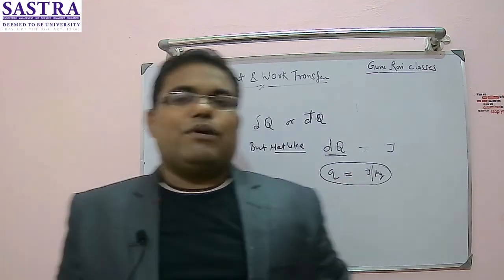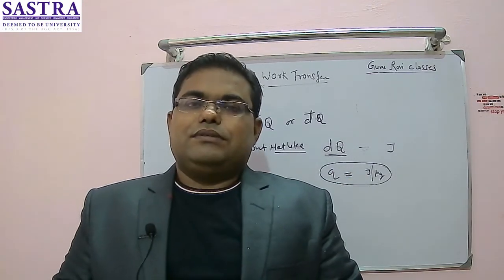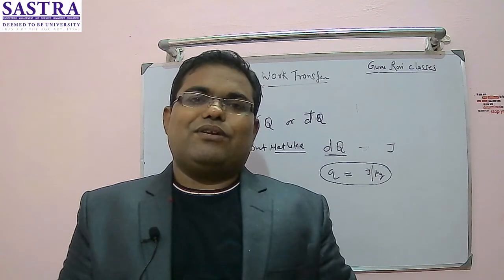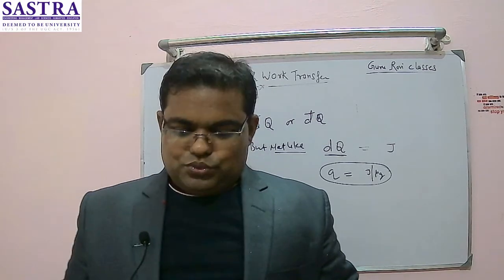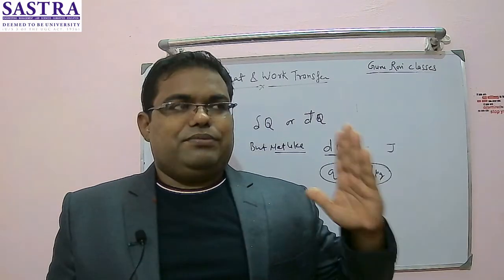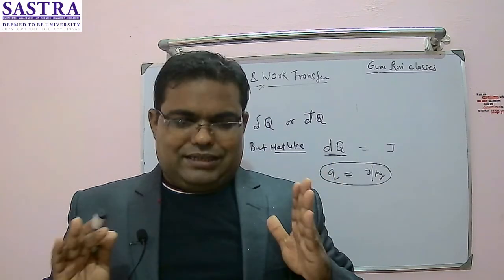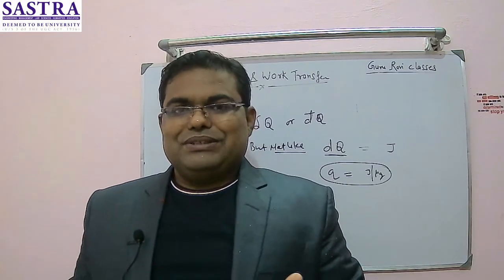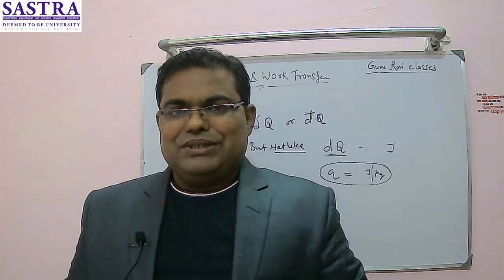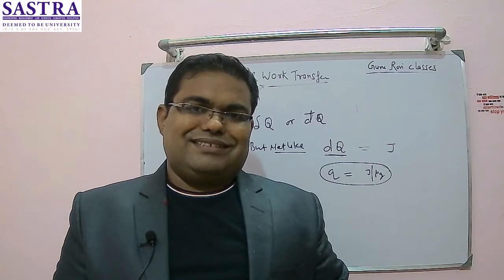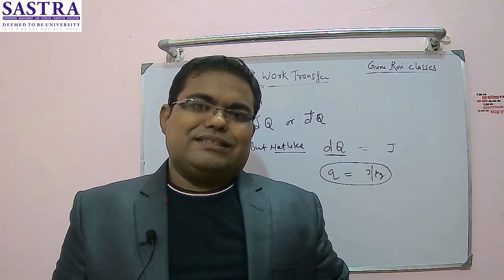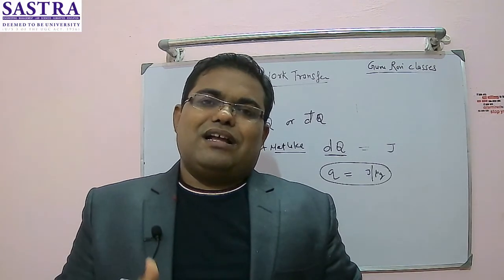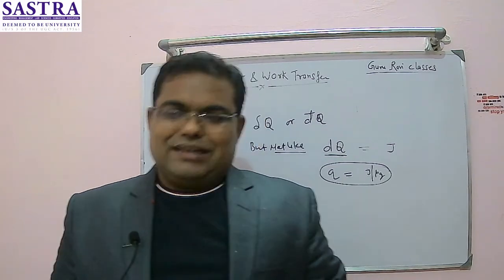So as I said, it is a boundary phenomenon. So one can observe heat only at the boundary. If the person is inside the system, he will not sense any kind of change due to the heat transfer to or from the system. If he is at the boundary, he can easily see there is something, heat, which is going into the system or coming out of the system. So it is a form of energy in transit. As it is energy in transit, that means it is not a property of the system, keep in mind. Like work transfer, heat transfer is also not a property of the system.